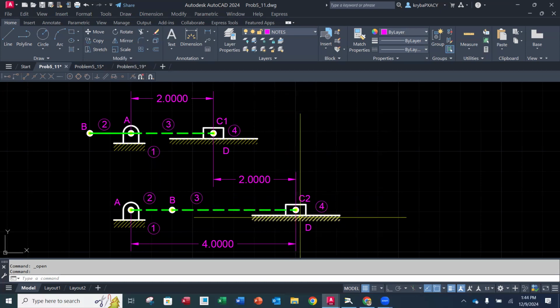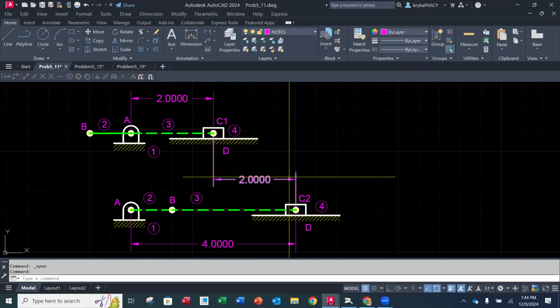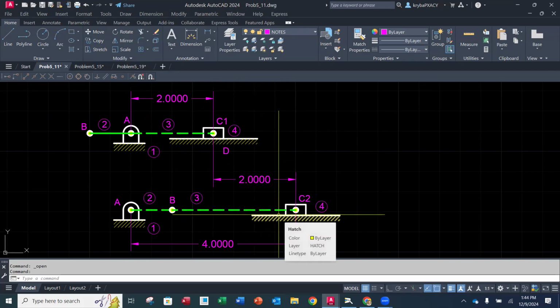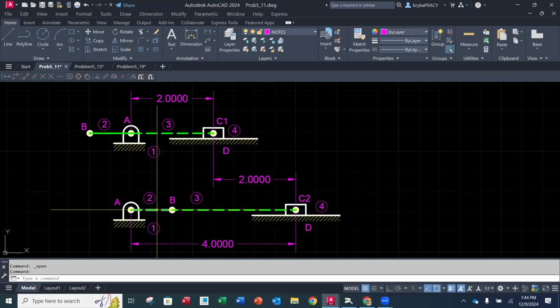now you're going to notice that it's in that position. Now these are in line. A is in line. The center of our crank rotation is in line from one to the next. So if I measure from C1 to C2, this is that stroke of 2 inches. Okay. And then what I did was I really laid those two out first. And then I went backwards.